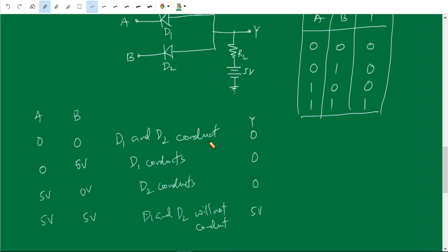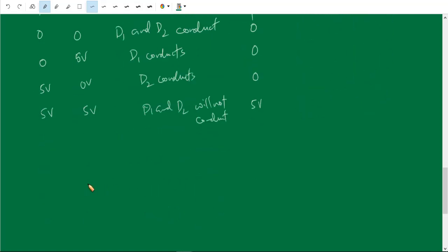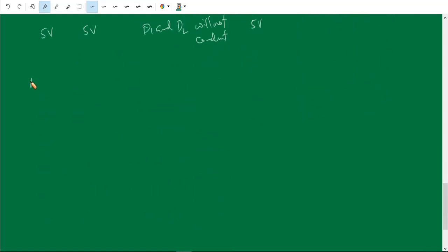Okay, now we wanted to discuss how a NOT gate works. So first let us see what a NOT gate is. A NOT gate has one input and one output. The NOT gate inverts the state from 0 to 1 or 1 to 0. It is also called an inverter. We can see the symbol first, the symbol of a NOT gate.